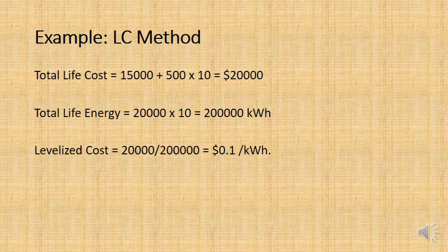Now, the levelized cost will be 20,000 over 200,000. That's going to provide a dollar value per kilowatt hour. And that comes to $0.1, or 10 cents, per kilowatt hour.